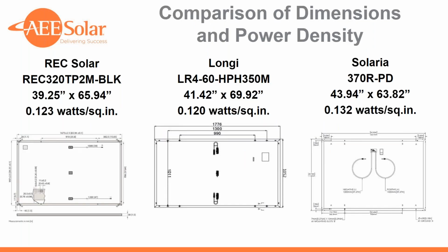So the next point I want to make here is a comparison of dimensions and power density. And I kind of pick on Solaria here a bit because it is a module that we've seen out in the market for years now, and I've done the comparison for folks on the size and what that means. This has been one of my sayings for a long time: module watts are not all equivalent, and you really need to look at the module area efficiency.